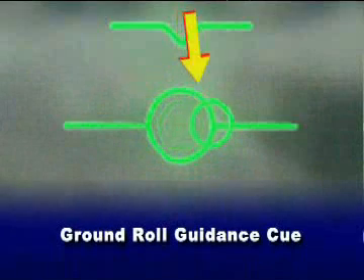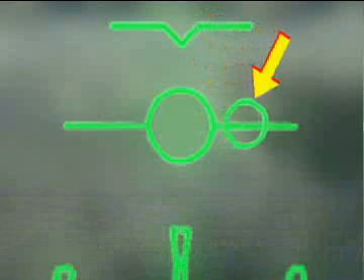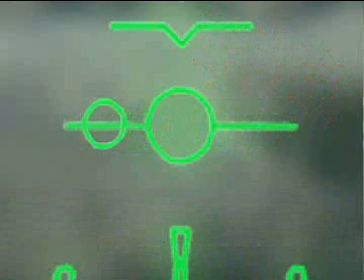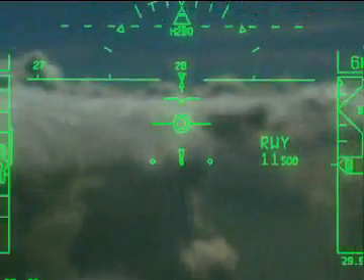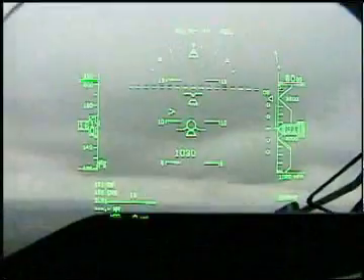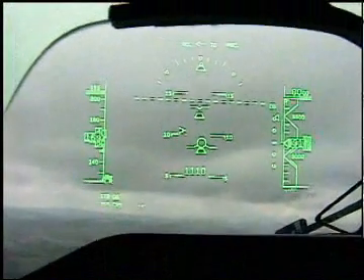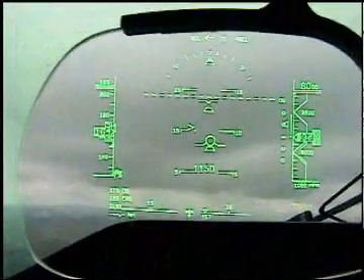When configured for a low visibility takeoff, a ground roll guidance cue provides HTS-derived lateral guidance commands relative to the ground roll reference symbol. This command provides for tracking the localizer during the low visibility takeoff roll using rudder control inputs. After rotation and the transition to in-flight, the ground roll guidance cue is removed from the display.